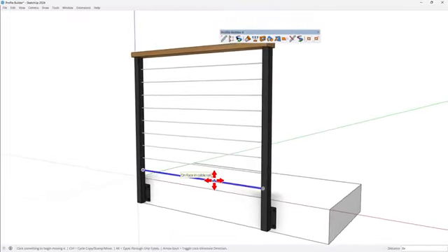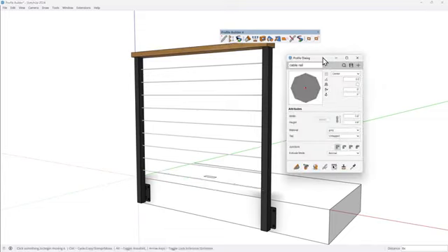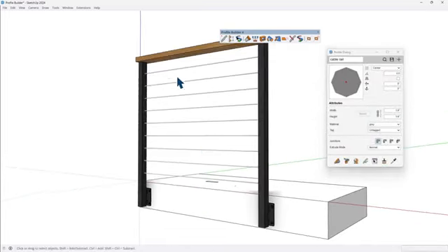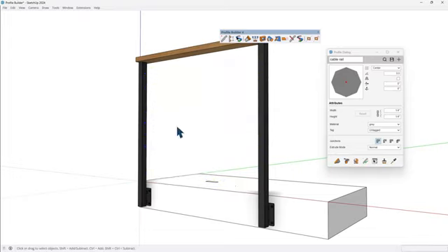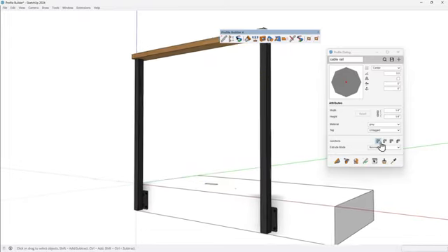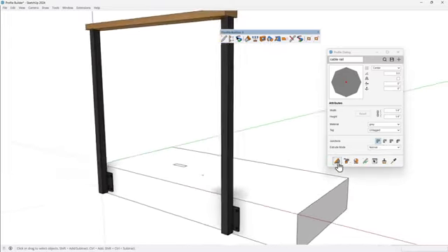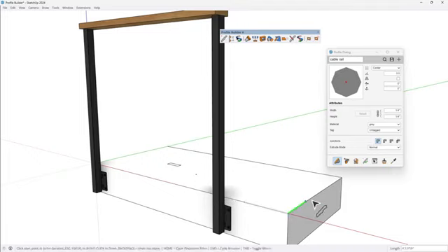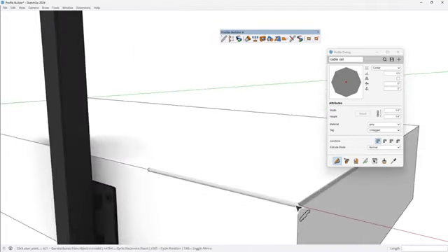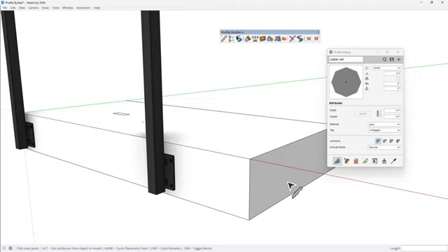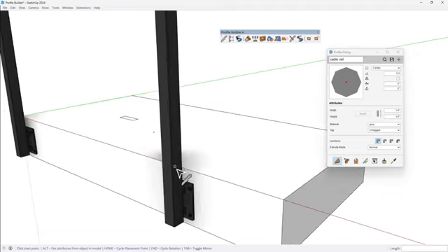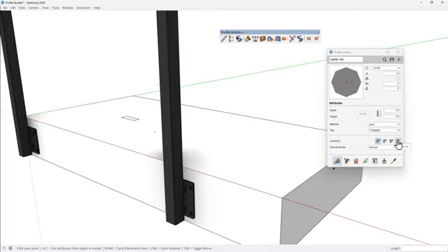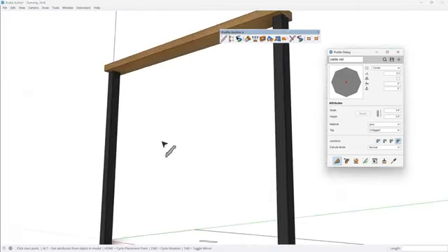Now you'll notice I'm not worried too much right now about junctions and setbacks, but one thing I do want to fix, and let's actually redo this. So one little oversight, junctions. So most cable rails, when you build them, they're going to miter and continue at that edge. But for the instance that I have where this piece needs to stop and then start, I'm going to set the junction to be none.